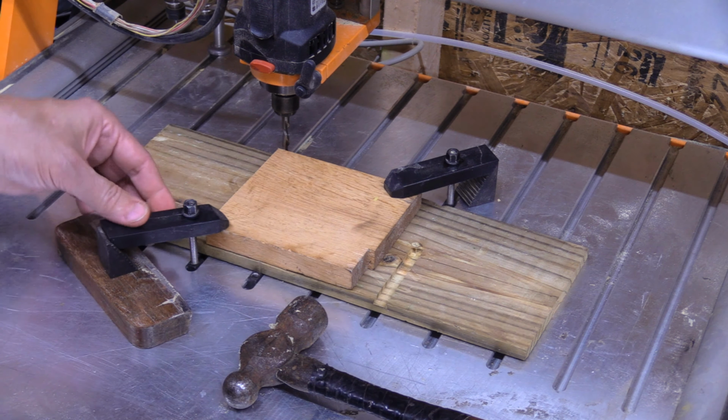So I want this to start at X minus 15. So I'm actually going to go back. I'm going to go back to 18. I'm going to go back to, let's see, 20. G1, Y20. All right, and I'm going to set my 0 there. So then when I go to G1, Y minus 15, I'm going to be just a couple millimeters off the edge of that board.